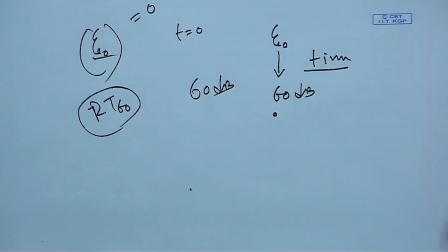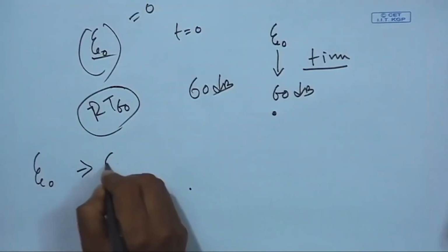Have I explained clearly? Suppose I switch on a loudspeaker in here for a certain time, so that the steady state energy density in this room, psi 0, is developed. Now, I switch off the loudspeaker. Then and there it cannot be 0, so it requires some time to drop the sound level. Reverberation time is defined as the time, from t equal to 0 when I switch off the loudspeaker, by which the energy density of this room has dropped by 60 dB from psi 0.